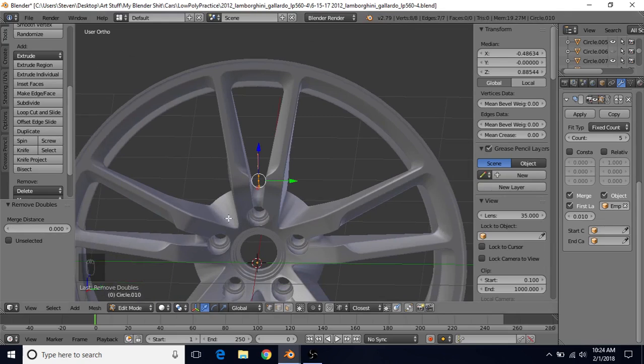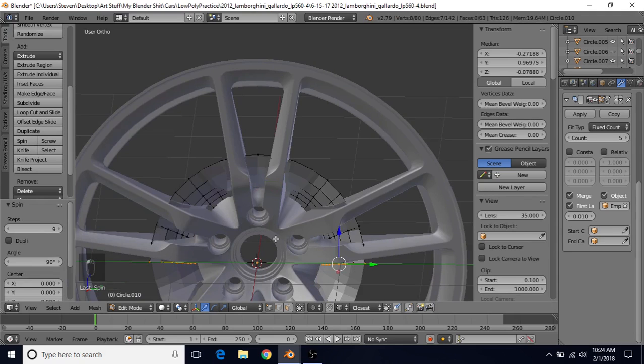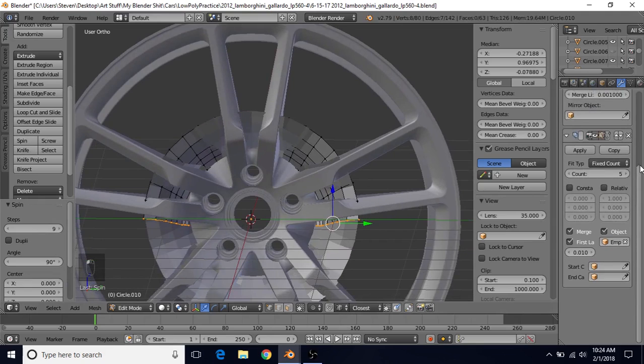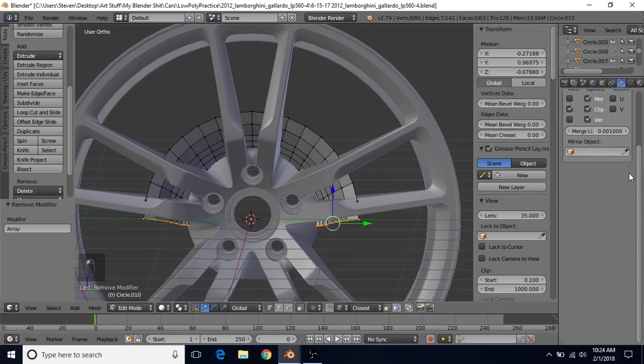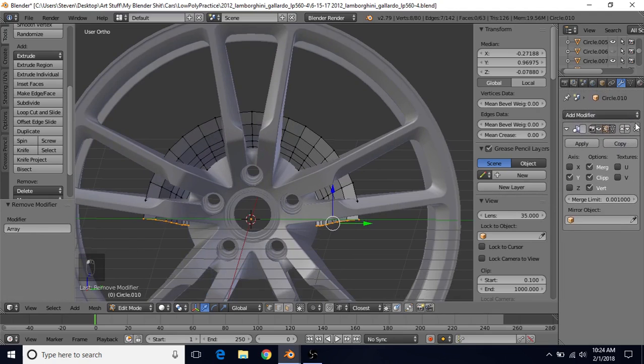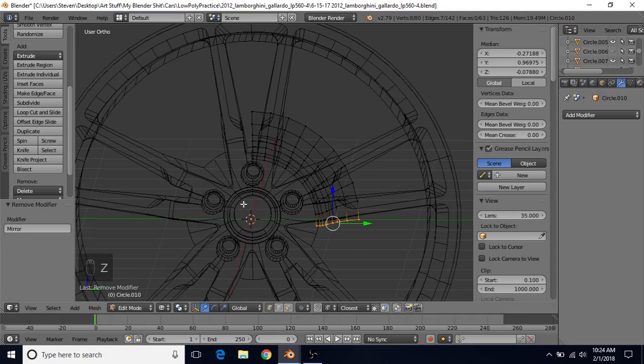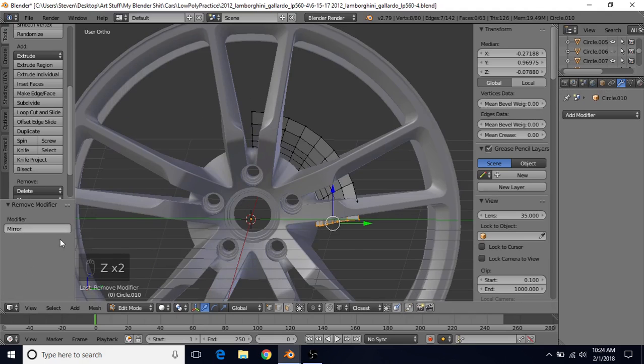So what we're going to use is the spin tool. We're just going to go over here, click on spin, it's in tools, click on spin. By default it does 90 degrees. And also we still have these modifiers that we don't need, so over here we're going to click the X, and then over here we're going to click the X. We don't need the modifiers for this. And that's actually going to get rid of the little spin tool options.